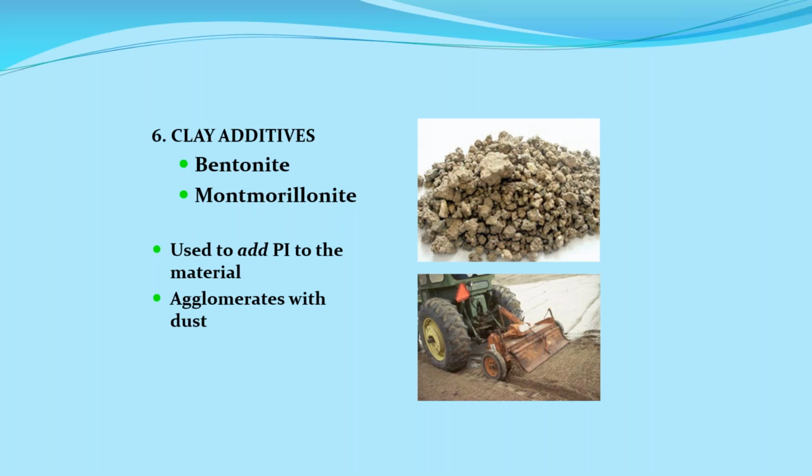But as a rock, it doesn't have any clay in it. So a lot of times we'll ship clay in the form of bentonite, dried bentonite. Up in the central part of Idaho, they ship in truckloads of dried bentonite and then mix it into their belt feed as the rock is coming out of the crusher, to increase their PI and be able to hold their material down.